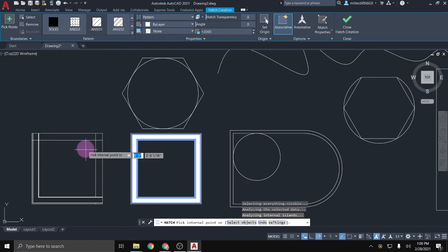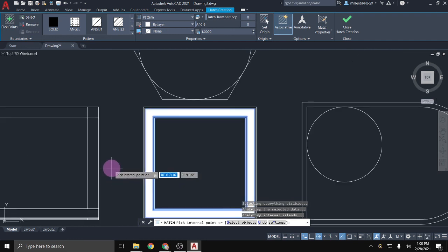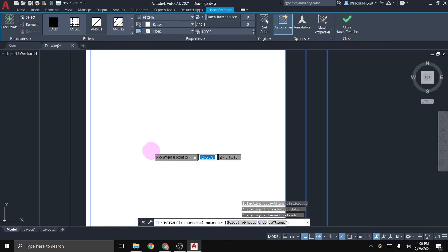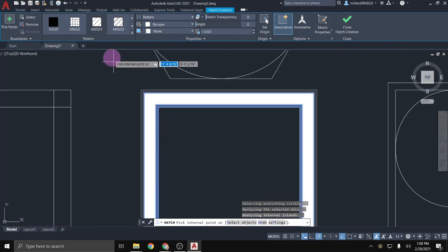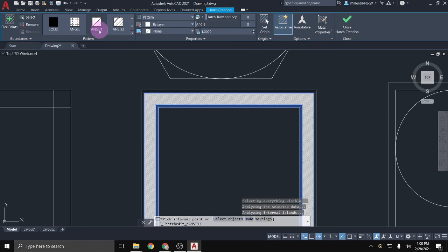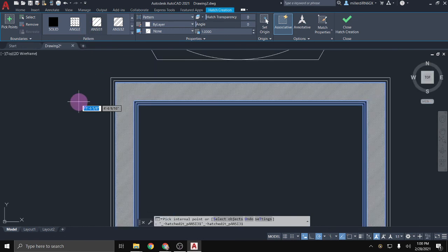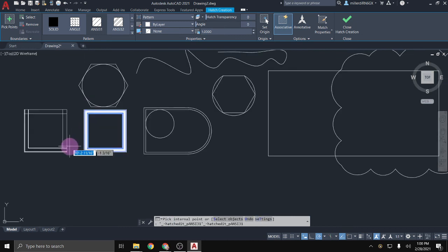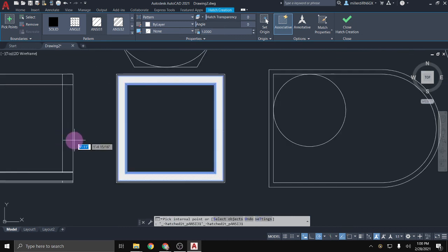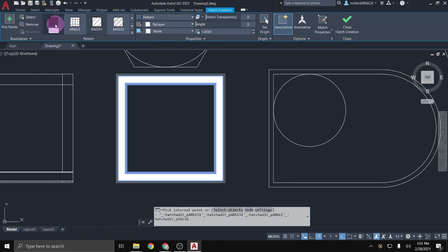The problem I see happen 99% of the time in architectural drawings is when I ask students to do a solid hatch and they fill it in with this. This is not solid. If I zoom in to it, it's actually doing diagonals. It is not solid, it's diagonal lines. Not what I want. I want it solid. When I zoom out, yeah, sure, that looks solid, but it's not. And so that would be changing this pattern here to just say solid.